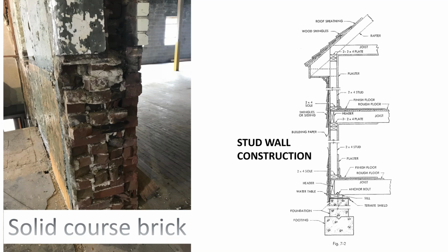Exterior walls are typically a stud made out of 2x6s or 2x4s, and then they either put vinyl, aluminum, wood, or brick on the exterior, so it's just a facade. That brick wall has no support value at all. It offers no more support than a vinyl or an aluminum sided house. Whereas a 4-course brick wall is going to be very comparable to a concrete foundation wall because it's 4-course brick thick, right?